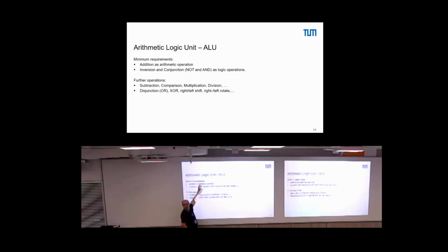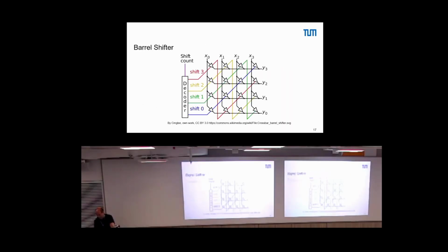But it's inefficient if you do not have more. That is why we want to have more, either within the ALU or close by. So addition, subtraction, some shift operation, something like this is commonly in the ALU. Something like multiplication, floating point multiplication may come as a separate accelerator. Okay, that's just a drawing of that. And then we had this barrel shifter, which I think there's not much to questions so far. This barrel shifter at the end, I just redraw this next to it.